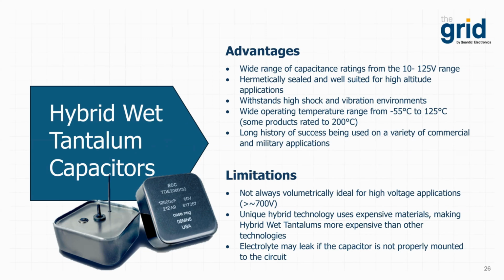Now, some limitations include the fact that they're not always volumetrically ideal for higher voltage applications. They do have their sweet spot. Unique hybrid technology does use expensive materials, making hybrid wet tantalum capacitors more expensive than other technologies. And similar to other types, they are filled with electrolyte, and the electrolyte may leak if the capacitor is not properly mounted to the circuit.